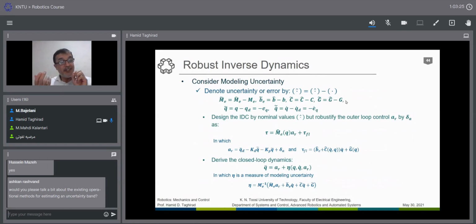And the gravity can be measured quite well, because if the gravity term is equal to 0, the robot will stay at the position it is in. So you can put some counterbalancing weight and then move it to different approaches and get the values of the counterbalancing equation, and then you find the difference between G and G hat in the real values. So for how many experiments do you do that? As many as you can.